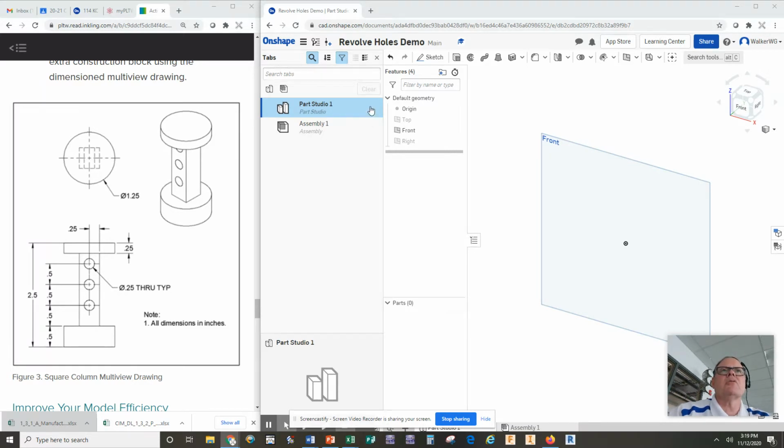So I'm going to start, if you look at the half rectangle here. If I'm going to revolve the bottom, I need half of this rectangle. The whole width of it is the same as the diameter of this cylinder, which is 1.25 inches. So half of that would be 0.625. The height of the rectangle is half an inch, 0.5.